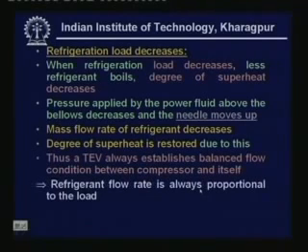That's why this is a very effective expansion device. The refrigerant flow rate is always proportional to the load. That is the reason why the thermostatic expansion valve is most versatile and very effective. It is something like a closed loop control. It takes the feedback from the feeler bulb and takes a corrective action, and this corrective action is in line with our requirement. That means when the load increases, it increases the flow rate to meet the increased load. Similarly, when the load reduces, it reduces the flow rate to meet the reduced load. So in addition to providing the required pressure drop, it also controls the flow rate in a required manner.